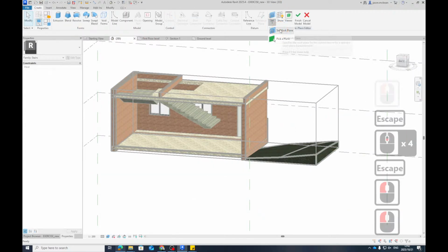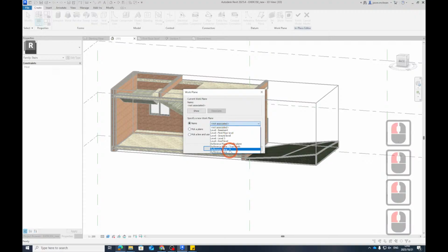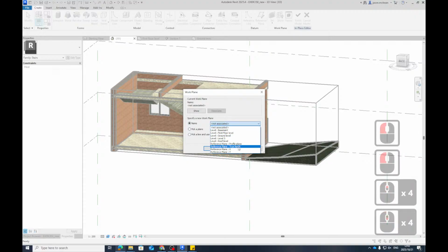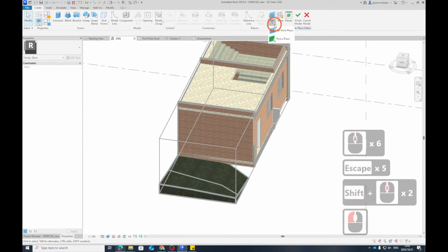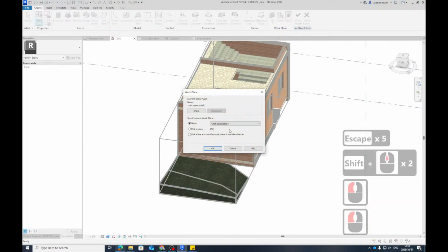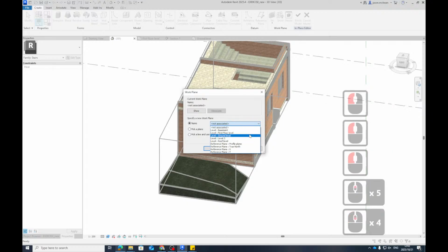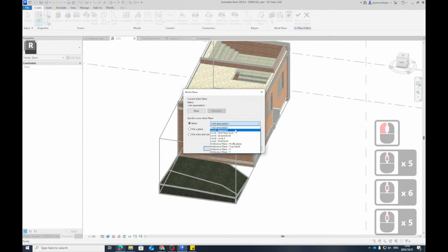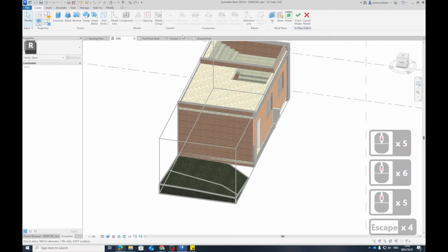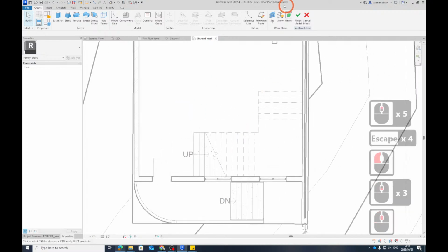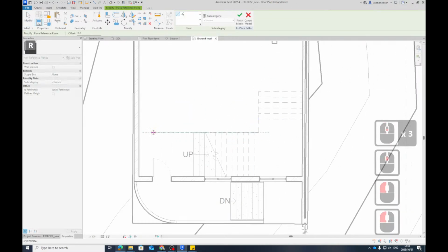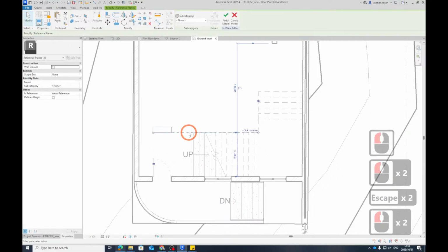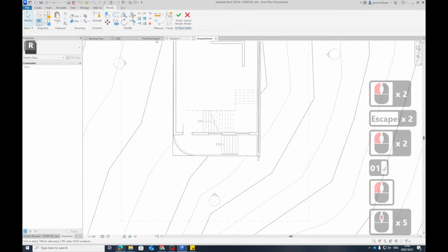Set Work Plane. You'll see it now. It'll be available. Reference plane. I'll call it 01. Set Work Plane. Reference plane. Oh, you know why? Because I made the reference plane inside of that. Ooh, Jason. Sorry, my bad. I'm working a bit faster. 01. Good. Now, 3D view.